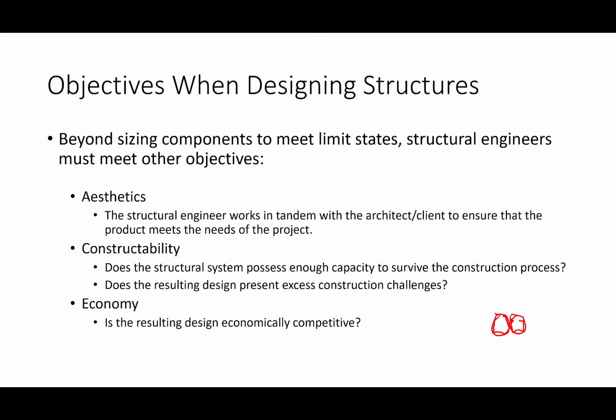Imagine trying to get a socket wrench around this bolt, right? It's knocking into this one, right? So the bolts have to be a certain distance apart so that you can actually get a wrench around it and tighten the bolts, right? There is a minimum bolt spacing, okay?